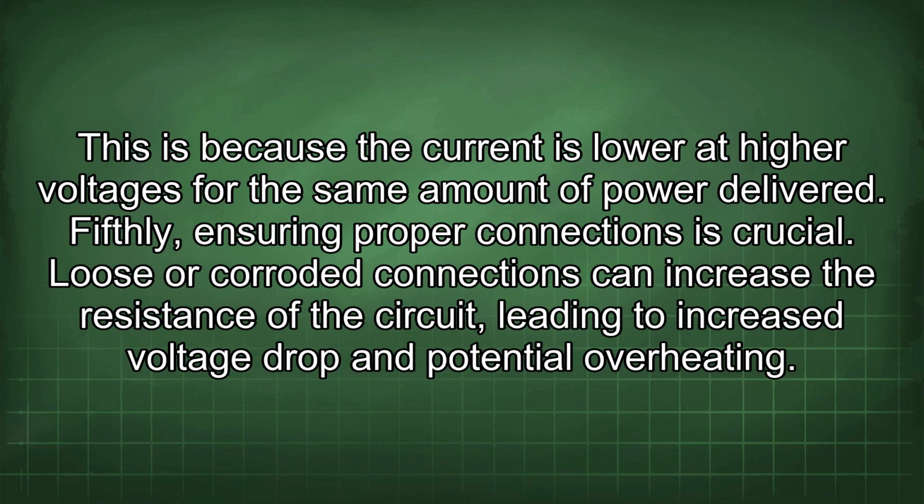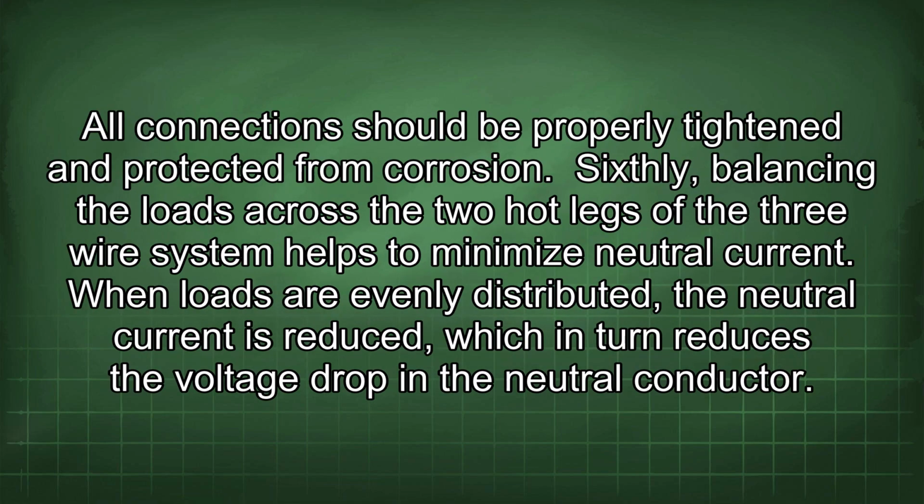Fifthly, ensuring proper connections is crucial. Loose or corroded connections can increase the resistance of the circuit, leading to increased voltage drop and potential overheating. All connections should be properly tightened and protected from corrosion.